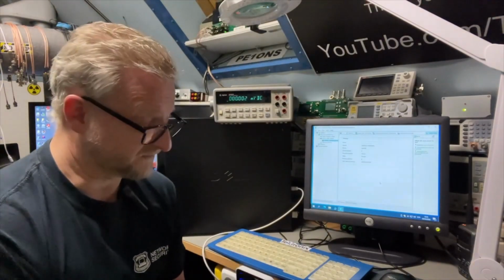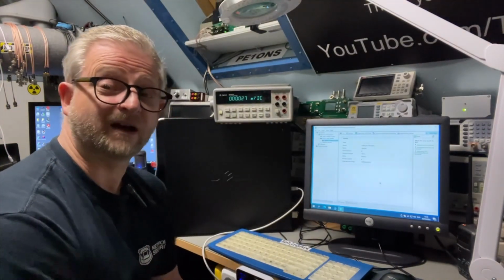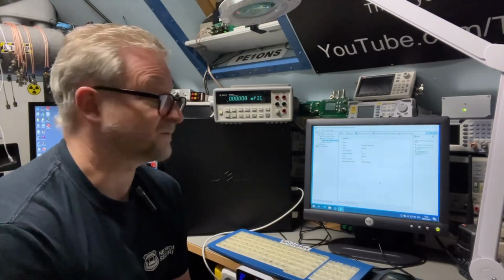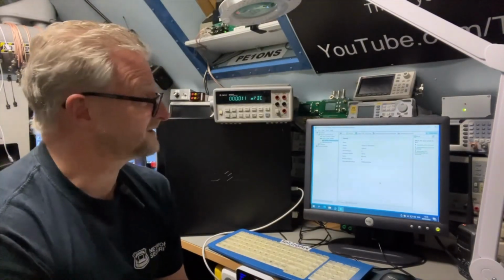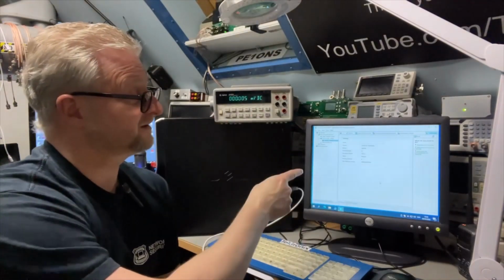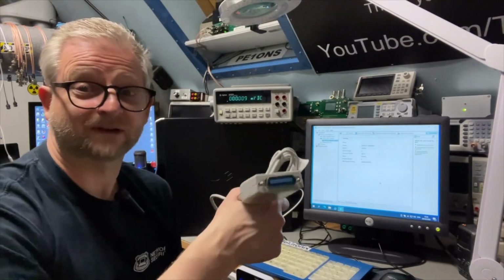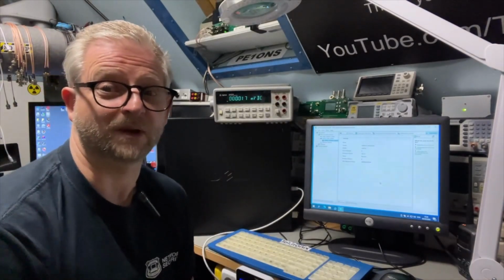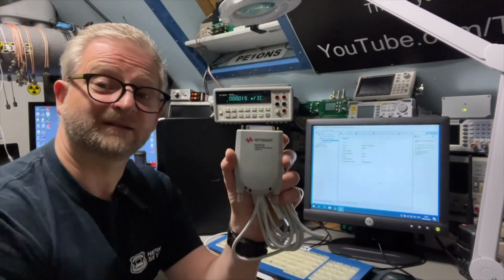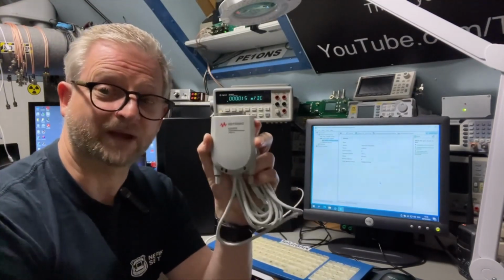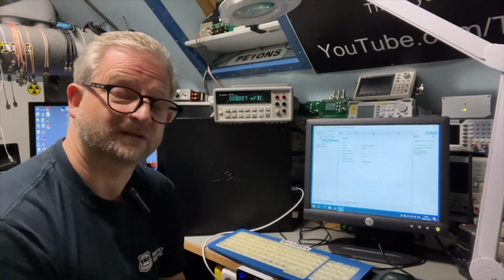What I did read is that Keysight has its own VISA drivers, and they are not always 100% compatible. So what you can do is first install the National Instruments VISA driver. It will not recognize the hardware, but that's no problem. But at least the VISA is then installed. Then you install the HP package or the Keysight package with the USB driver for this device.